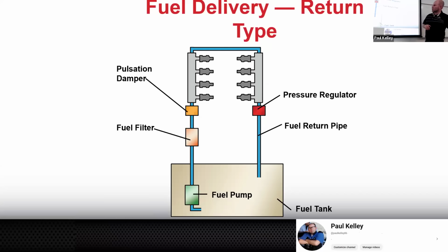The other thing is it's a rubber diaphragm. If a rubber diaphragm tears and a vacuum line goes there, where do you think the fuel goes at the end of the day? Exactly. It'll pull through the diaphragm, get sucked up by the vacuum line, and it'll start adding fuel in a sneaky way. Okay, so I want you to remember this.